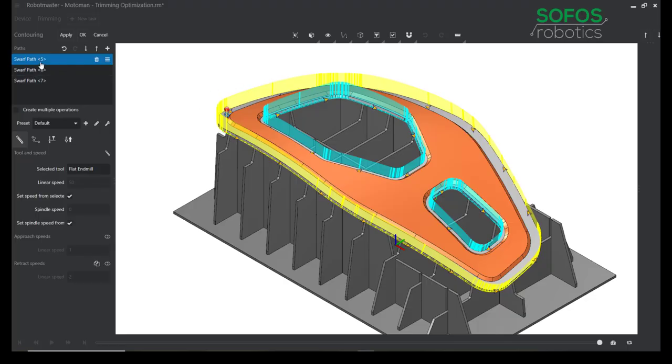So one thing that's helpful is I can change where I want the start point. That is indicated by this red pin. I can left click and drag this to wherever I want it to be. I can also click this little chain link here if I don't want to do the entire path, and this will allow me to select the section of path that I'd want to do. So if I just wanted to do this much, I could left click, and you can see it would just do this much of the path, with the green pin being where it's going to start and the red pin being where it's going to end. I just went over how to reverse the direction, so if you wanted to reverse the direction, you could. I'm going to undo that.